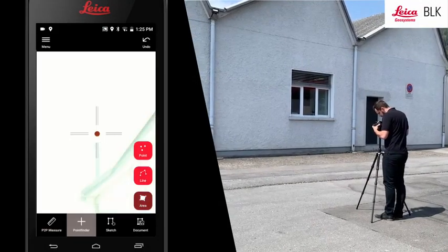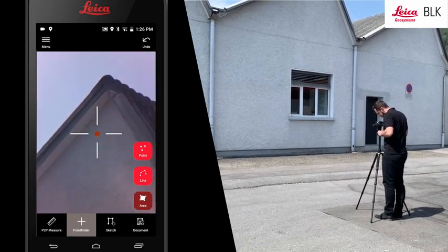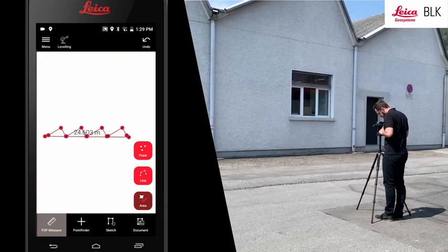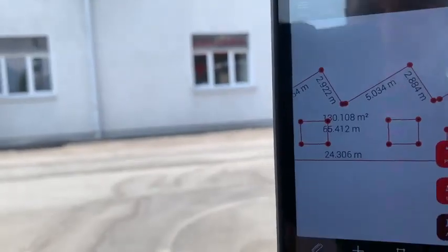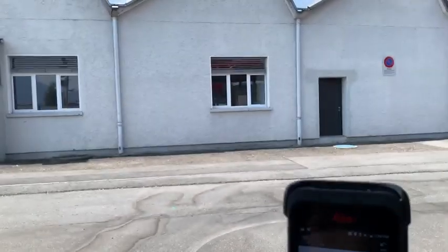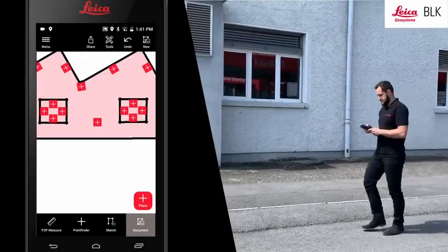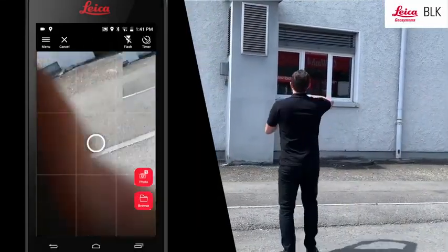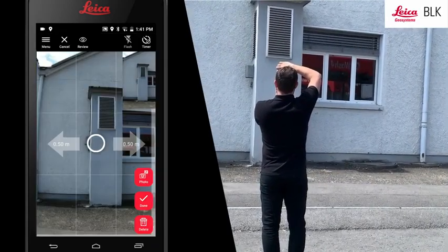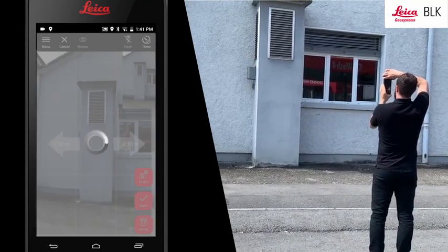You can switch between area, line and point to define any aspect of your facade. Direct the laser to your target and measure. On the screen, your facade will be drawn out. With the drawing being displayed before you, you can easily see what was already measured and where we are still missing dimensions. Now comes the best part, since on this layout we can attach measurable 3D images. This way, we will never forget any measurements and will avoid guessing distances or returning to the site to remeasure.